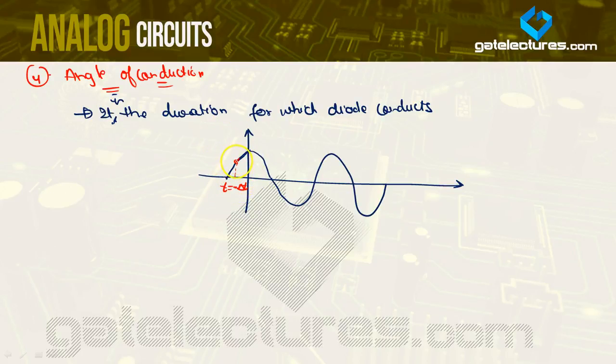Now at this point the capacitor basically charges and follows Vi. The capacitor charges and follows Vi. It must be discharging before t is equal to minus delta t. Now it is charging up to this particular point, this is 0, and then again it discharges like this. So we are considering this. Understood? Now for this particular duration, which is t is equal to delta t, it is charging, it is following